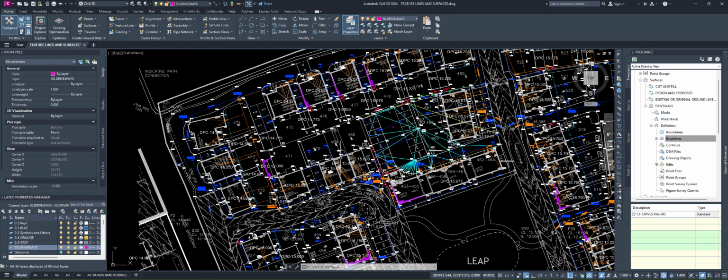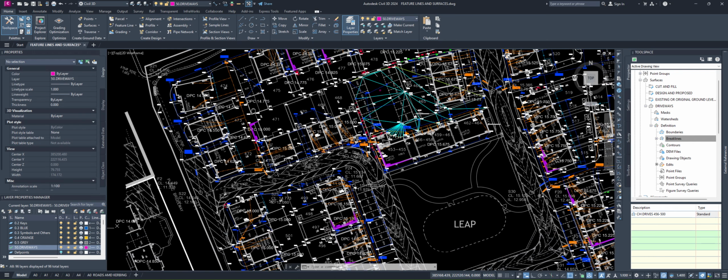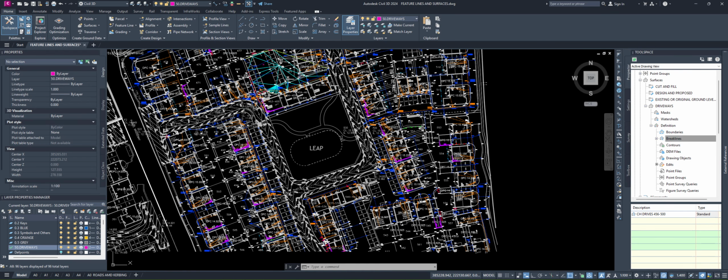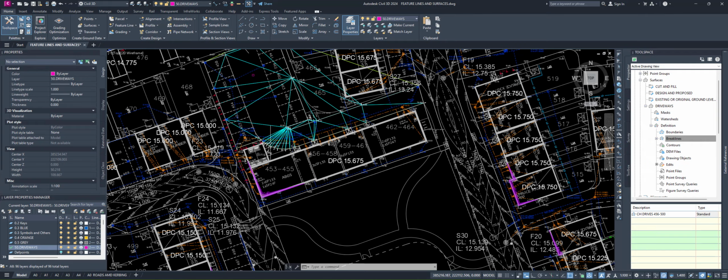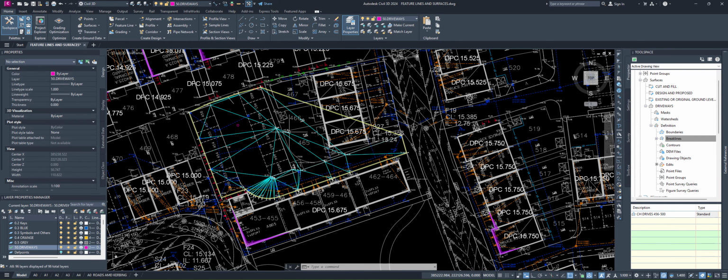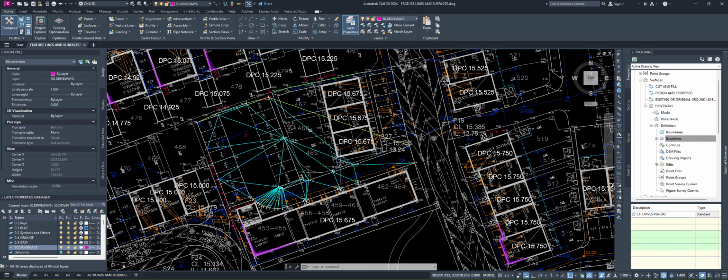So what you can do is redraw another driveway and put it under exactly the same surface. What's going to happen is you're going to create triangles joining the two surfaces, and you can just delete the triangles in between. But if you're going to use only that line work, you can use the boundary properties to instruct your boundary to cut everything outside your line work, to trim all the triangles outside.